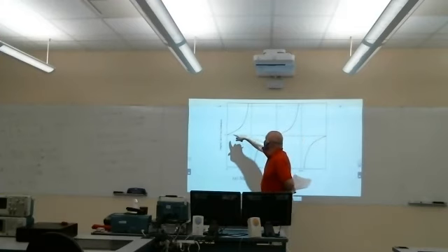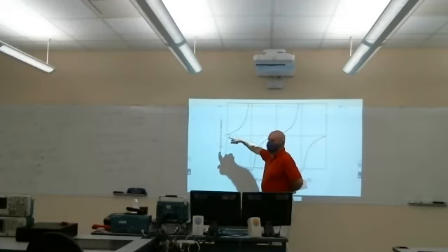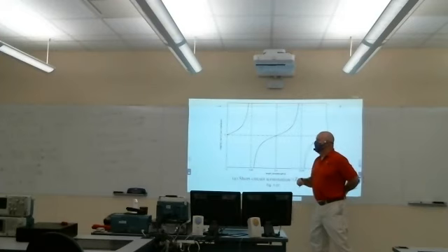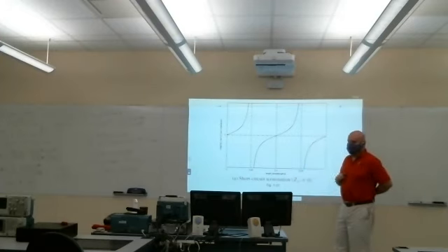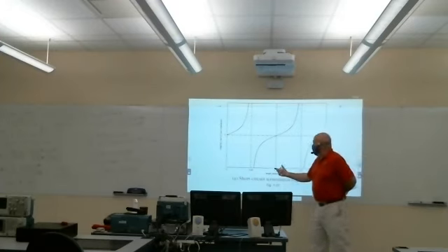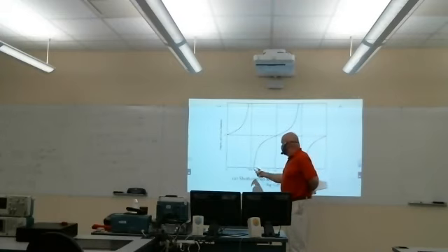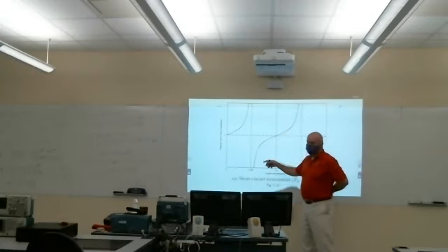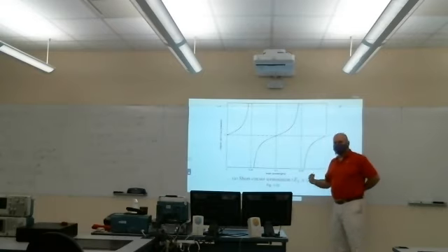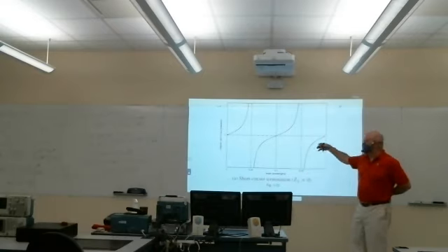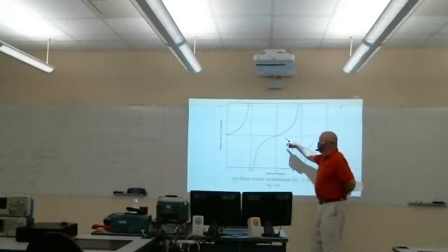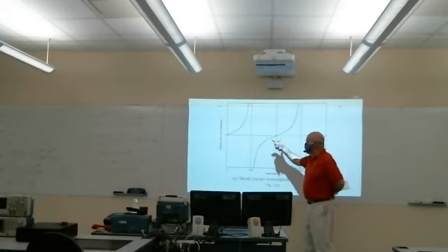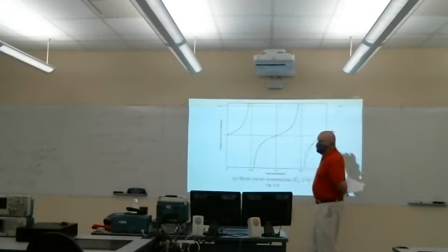And the inductance, I can get any value of inductance I want between 0 and infinity, actually. This would be any value of inductive reactance. And the next quarter wavelength interval, between lambda over 4 and lambda over 2 back from my short circuit, is capacitive. Again, with any negative capacitive reactance I want between minus infinity and 0, and then it's periodic at lambda over 2. And then this just repeats forever.